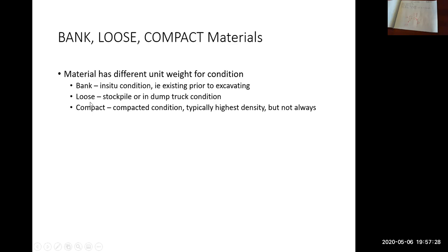So compact. As you take this loose material and you throw it back into the hole that you just excavated, you likely will not fill the hole back up if it's compacted. So compaction squeezes all the particles together to form a denser material.